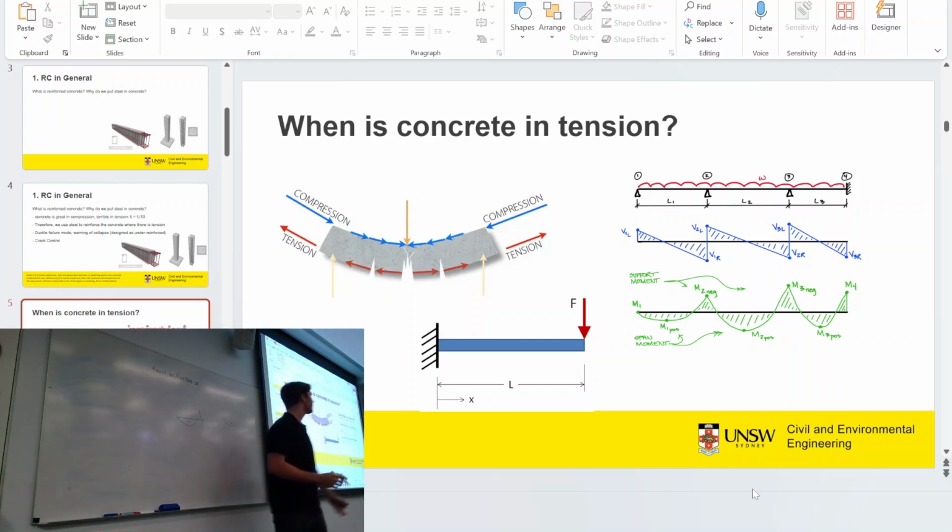No worries then. All that really matters is when a beam bends downwards, the bottom face is in tension. Just like here. So that's where we're going to put the steel reinforcement. That's the main concept. When the beam bends the other way, when it hogs, when it goes upwards, the top face will be in tension. Does that make sense?